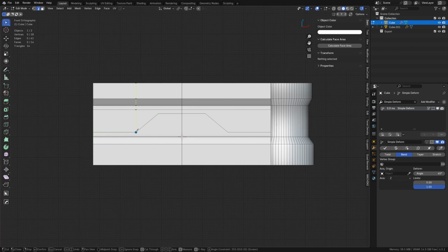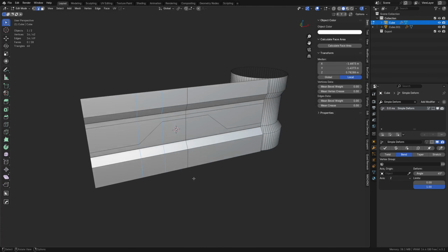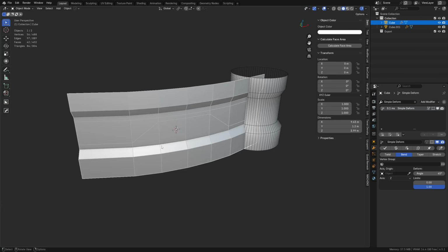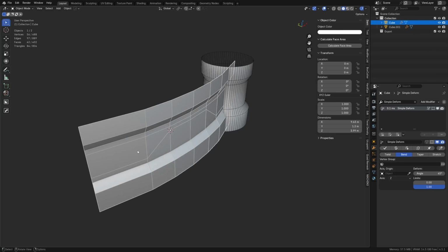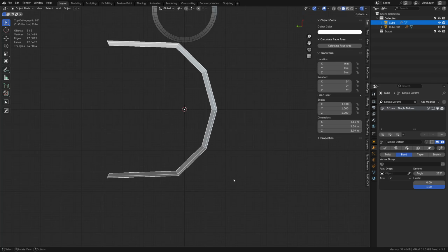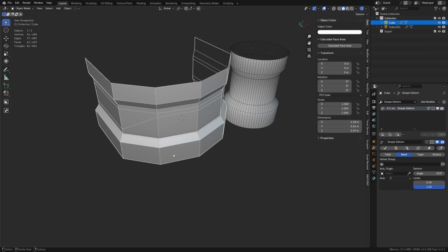So you have to add cuts to create a cylindrical shape this way, okay? Now the trick is they need to all be kind of evenly spaced vertical cuts. And it starts to bend correctly. Now, the problem is if you have the spacing wrong, they turn into flat spots, right? So you could do that for stylistic purposes or whatever you might be working on might need that. But in our case, we don't really want that.